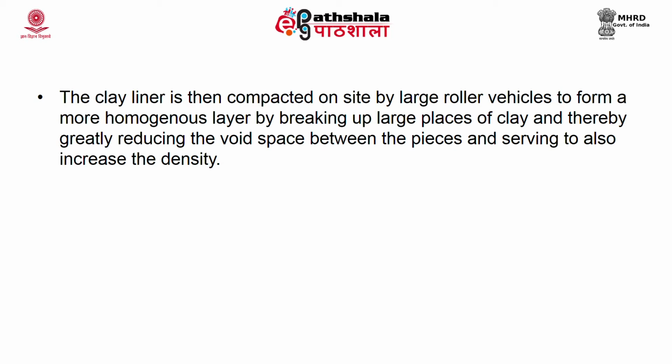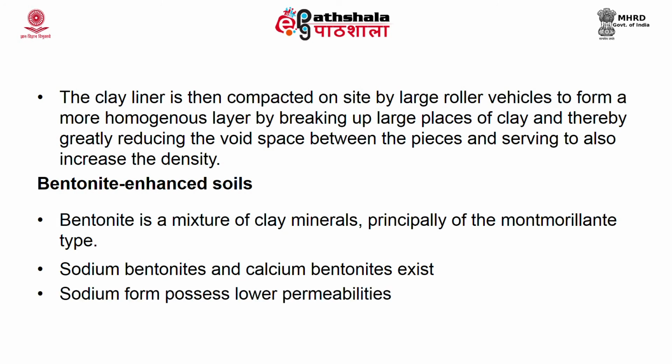The compaction will increase the density and help avoid the movement of leachate through that. Now, the next type of liner material is bentonite enhanced soil. Bentonite is nothing but a clay mineral, a mixture of clay minerals. Principally, it is made up of the montmorillonite type.